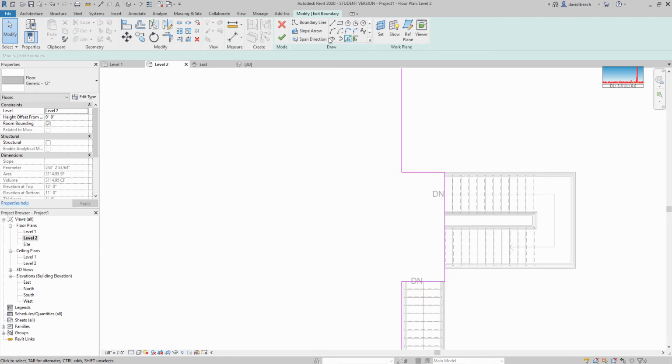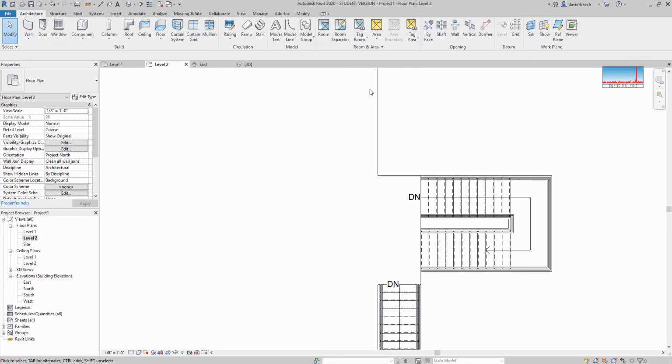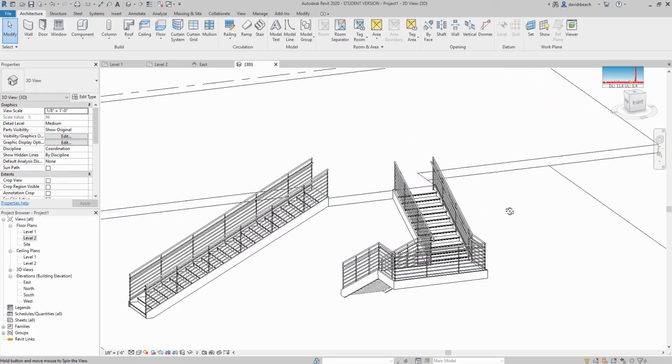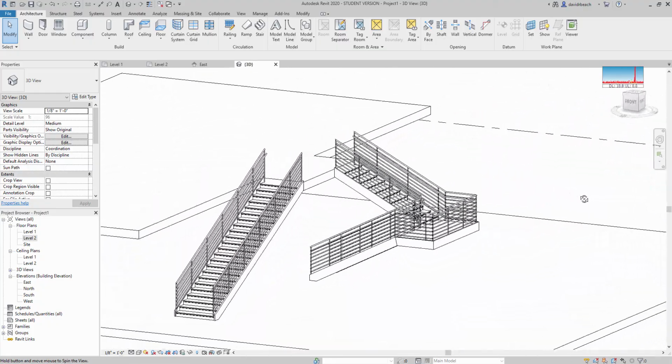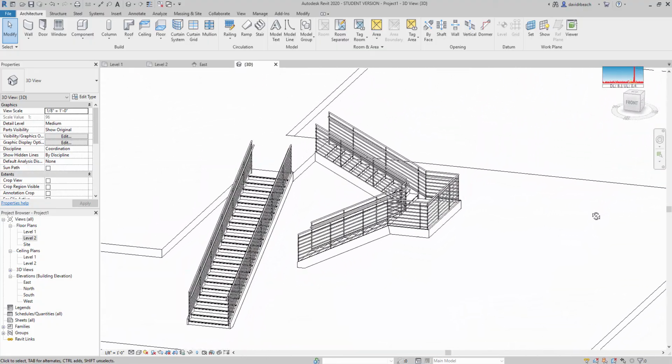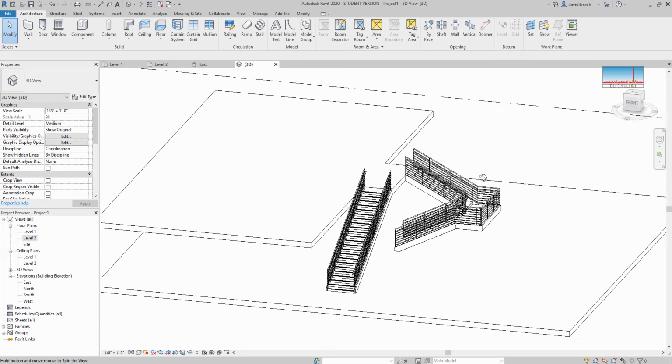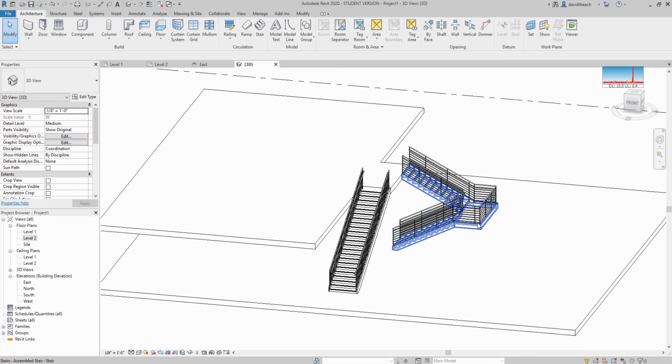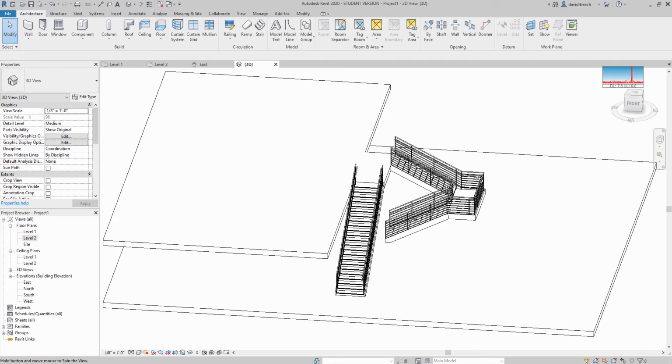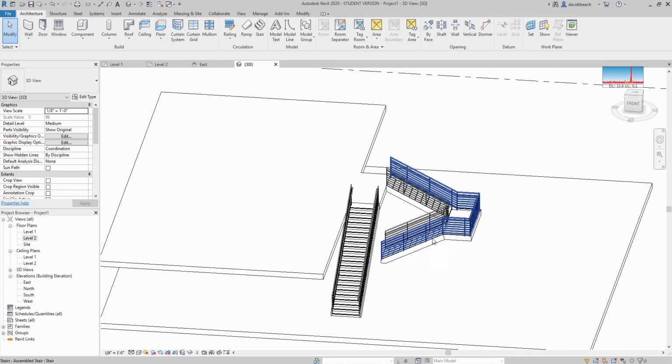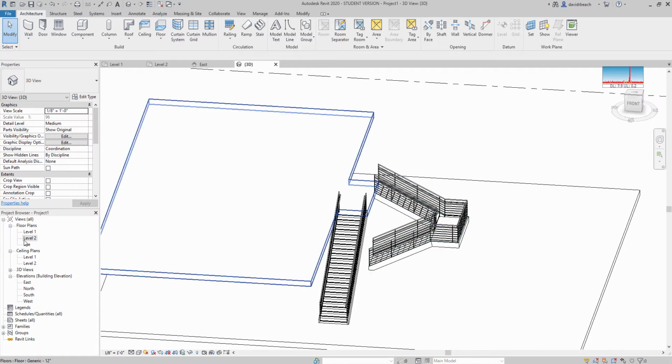So that all those pieces line up fairly gracefully. Okay, so I've got something like that, all done sort of with the default stair method. So the other way that I would build something like this, that I often like to do, is build the stair in 2 pieces. So 1 and 2.